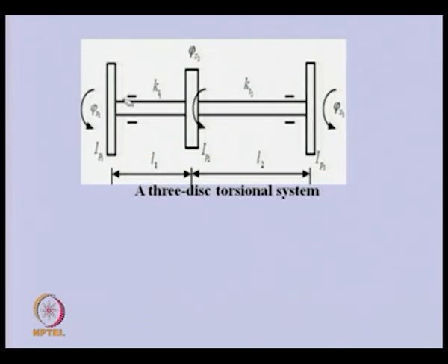So, during motion these supports are not preventing its torsional motion. So, this particular case is also similar to the free condition. The shaft between discs 1 and 2 has torsional stiffness Kt1, and the shaft in between disc 2 and 3 has stiffness Kt2. Dimensions are given here. The discs have polar moment of inertia IP1, IP2 and IP3 for discs 1 to 3 respectively.